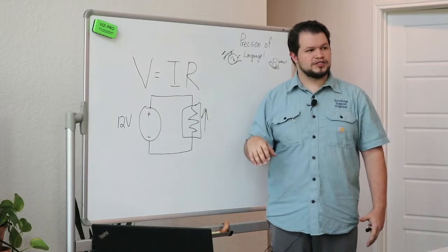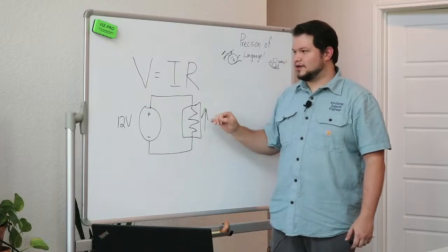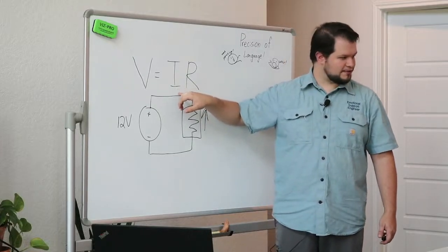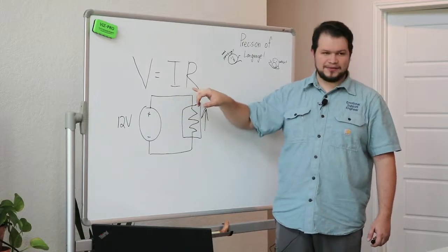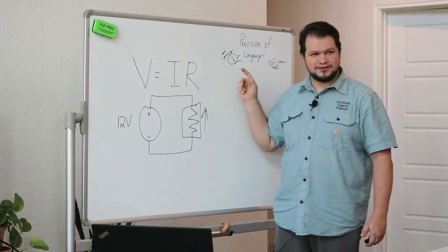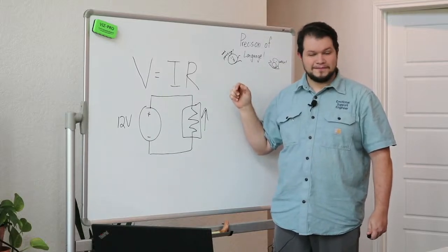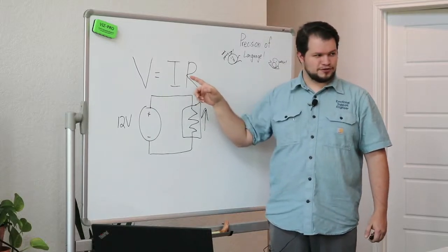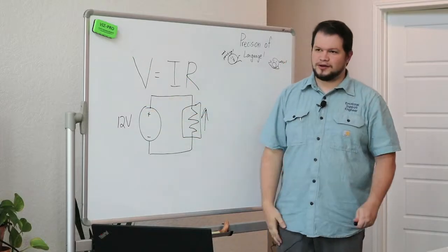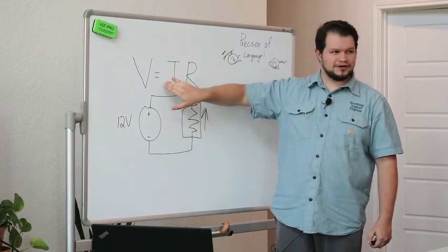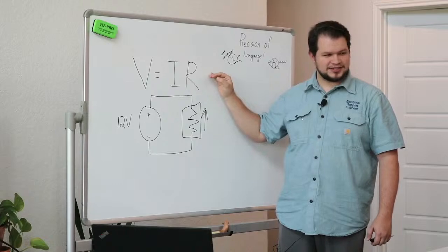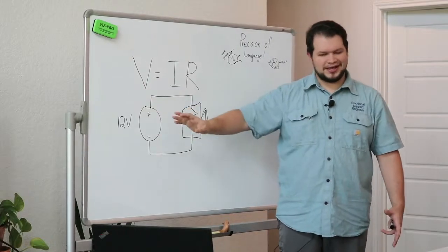Your battery can only supply so much current at one time. But what happens when you pull more than what your battery has? You've hit the upper limit on your current. You keep giving an increase on the load. What happens? Kill your battery. You do kill your battery in terms of you drop the voltage. If you look at your control hub, you'll see that your voltage starts dropping whenever you have no more current to give. And when your voltage starts dropping, well, then you've capped out and you're starting to do damage to your battery in essence.